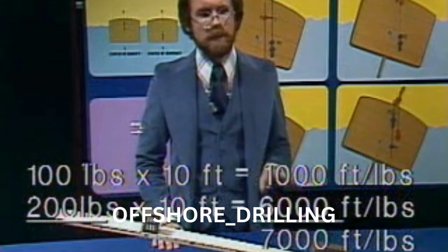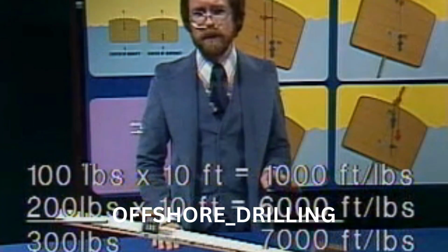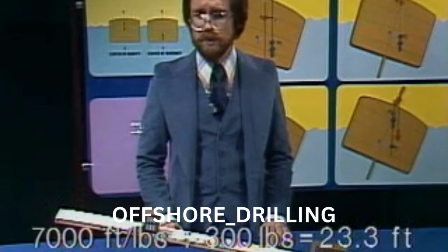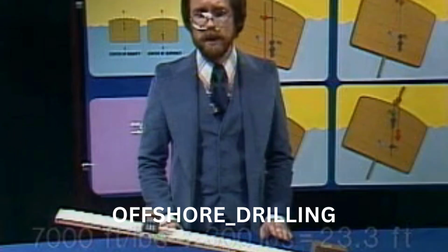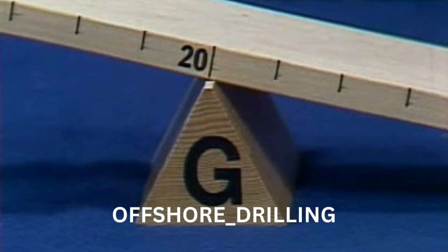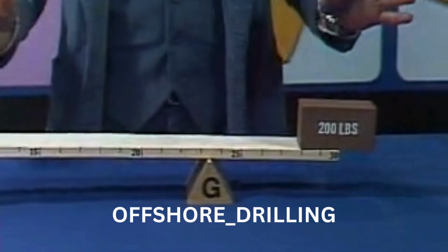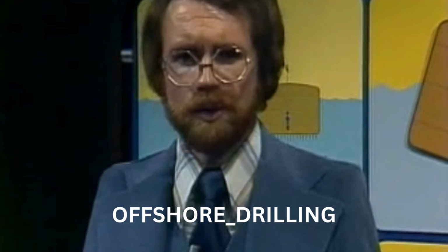Total moments are 7,000 foot-pounds. Total weights are 300 pounds. Therefore, 7,000 foot-pounds divided by 300 pounds equals 23.3 feet. This is the distance that G should be placed from point A in order to balance the seesaw. So, if we move G 3.3 feet to the right, the seesaw will balance.